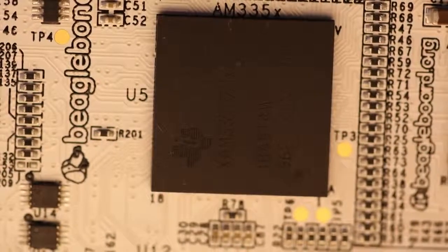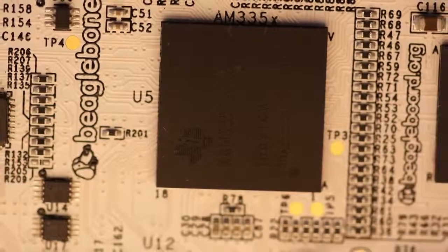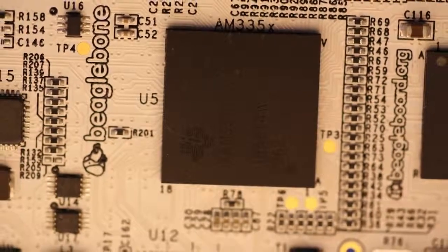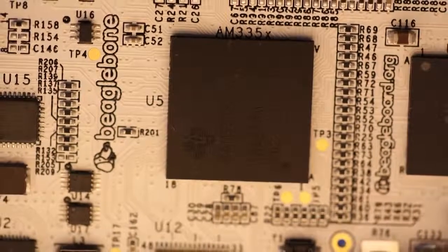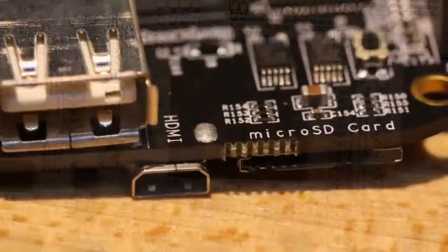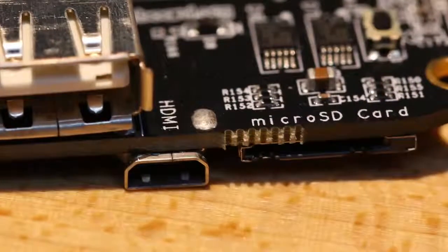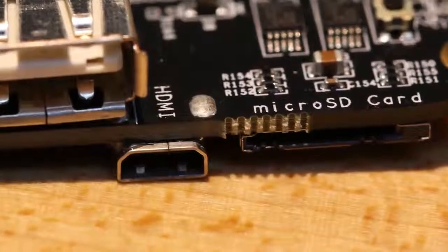Previously we did this using an OMAP MUX that was part of the Beaglebone distribution. However, since the 3.7 Linux kernel, that is no longer available. As the Beaglebone Black comes with the 3.8 kernel, this is an issue that's quite relevant. The new kernel gives the Beaglebone access to the Direct Rendering Manager, which is required for the new HDMI video output features. So why was the structure changed?